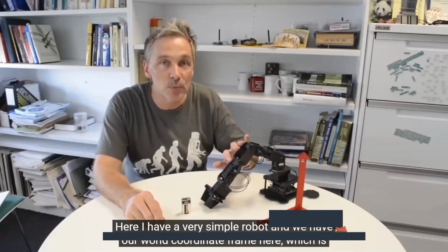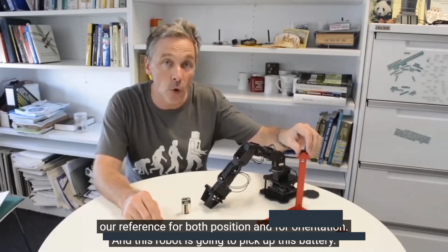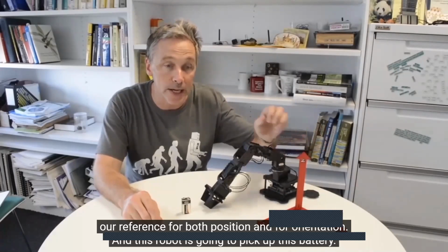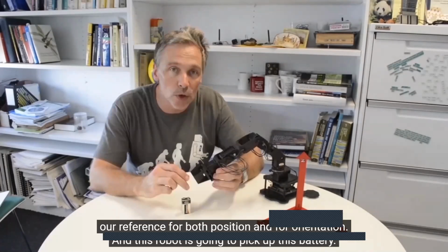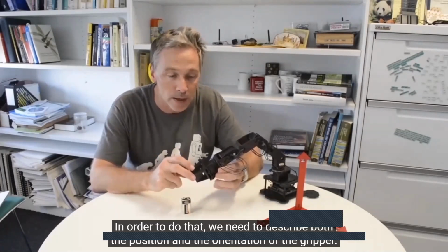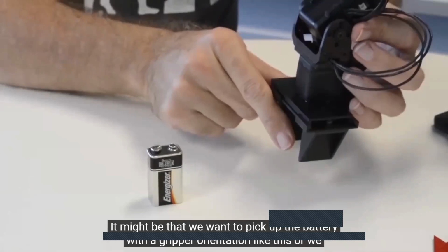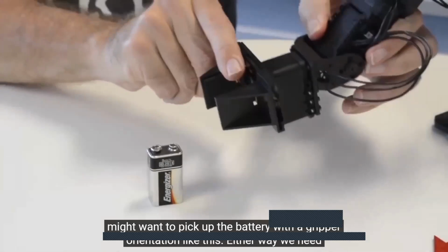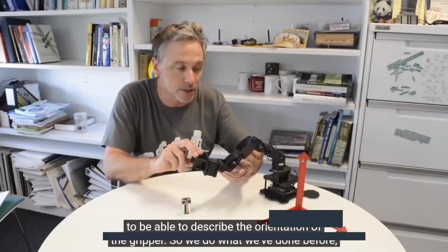Here I have a very simple robot, and we have our world coordinate frame here, which is our reference for both position and for orientation. And this robot is going to pick up this battery. And in order to do that, we need to describe both the position and the orientation of the gripper. It might be we want to pick up the battery with a gripper orientation like this, or like this. Either way, we need to be able to describe the orientation of the gripper.